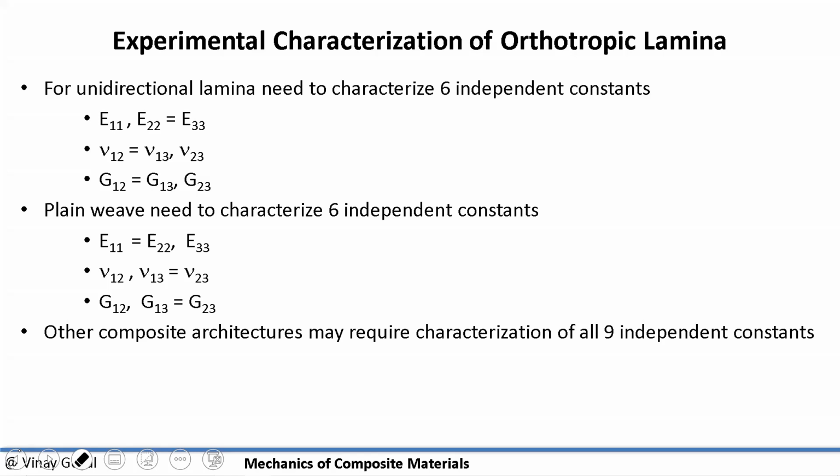I can click here in the view data spec sheet and see more data. I see that the tensile modulus is 34.8. And they provide other composite properties if this was within a resin system. So it tells you estimated properties if this was within a resin system, which can be very useful. But for now, we're going to choose 35 MSI as a starting point.